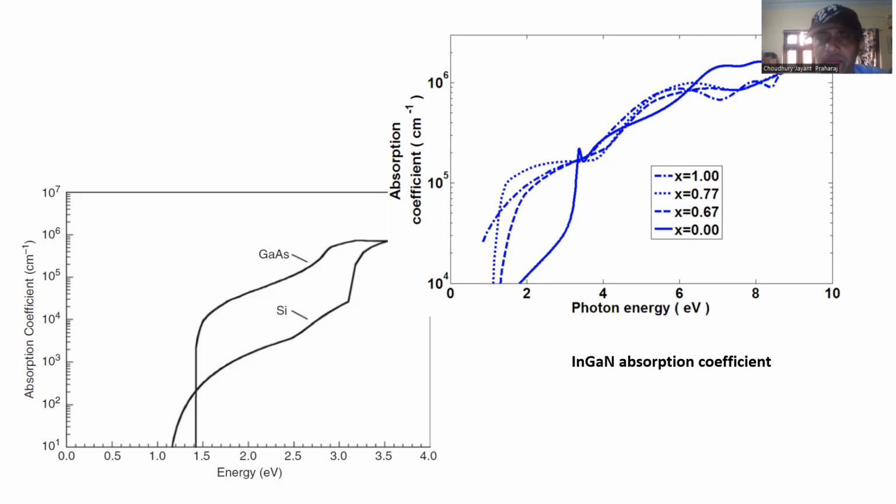and the barrier width. Now, the thing to keep in mind is that for the P-type material, it can become difficult to obtain good contacts in these semiconductor systems. So what happens is that the acceptor binding energy in these materials is fairly high, something like 150 millielectron volts, which is much higher than the thermal energy at room temperature, which is 25 millielectron volts.